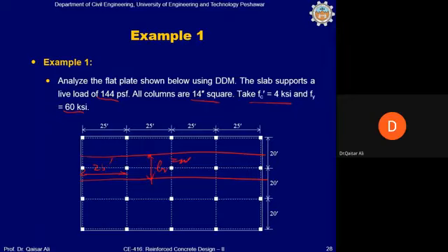So you will be considering 25 feet, not 20 feet, for the selection of size. However, if you are considering the other direction, then you can take L as 20 feet. However, regardless of the analysis of the frame in one or both directions, the slab is the same. So usually you will consider the slab thickness as uniform in all the panels, and it will be calculated based on the maximum length, which is 25 feet in this case.